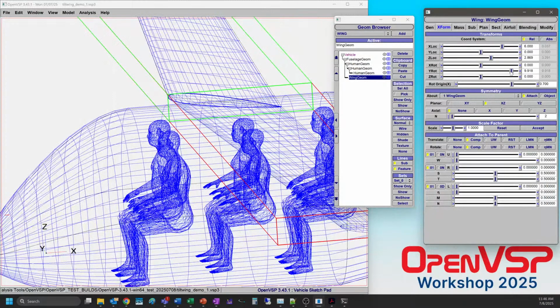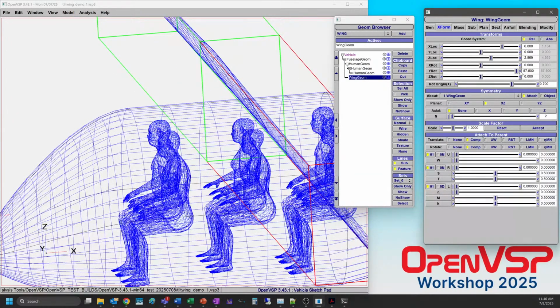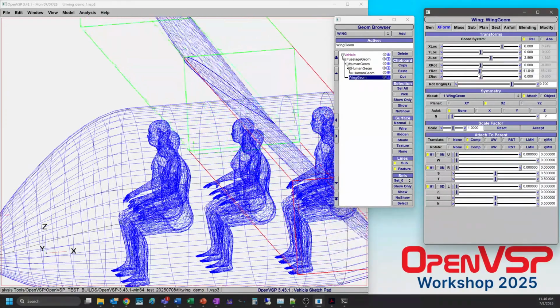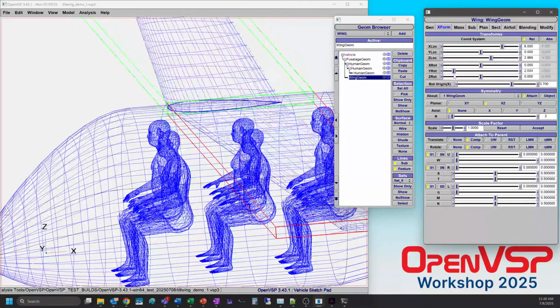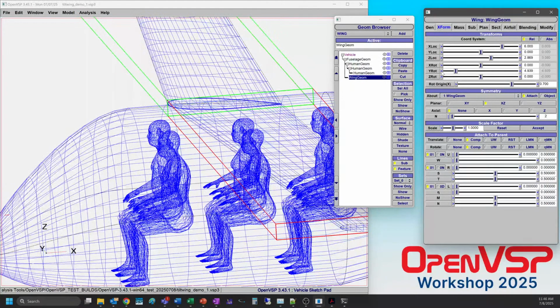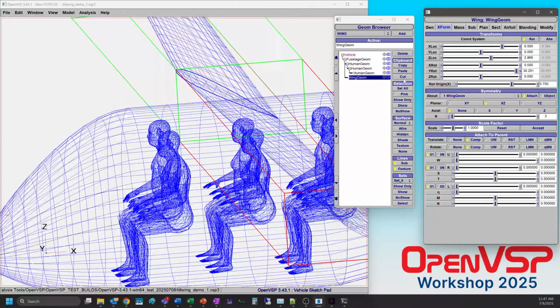And if you notice, as I'm coming up against this button here, it's changing from an inside arrow to an outside arrow. Anyone that hasn't seen this behavior before, if you click on this, it increases the range of the slider. So now we can go all the way up to 90 degrees or beyond and rotate down. So we can go as far or as short as we want. If you find that that range is too big, simply click on the collapse button and that will shorten the range. Now we have a smaller segment that we walk through.